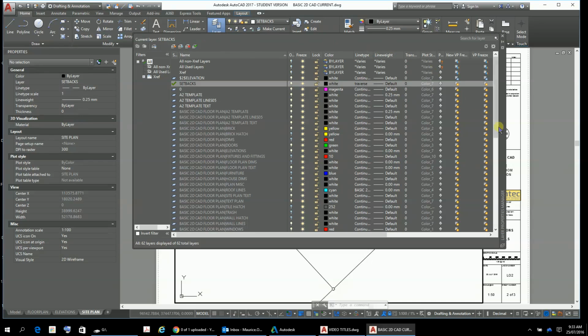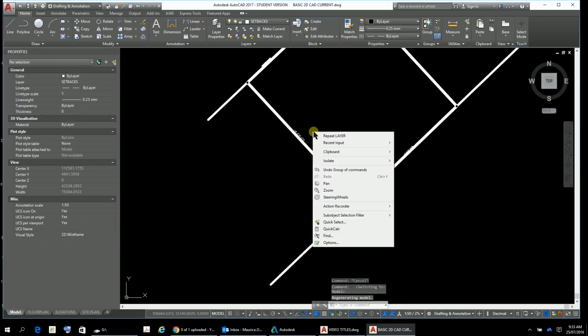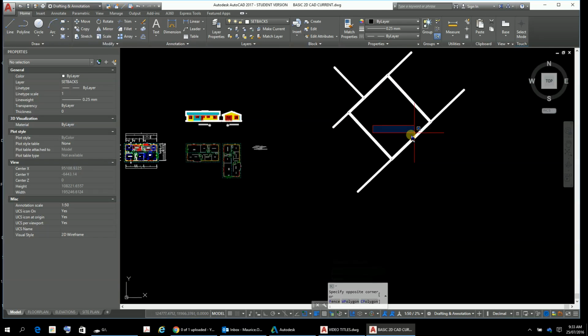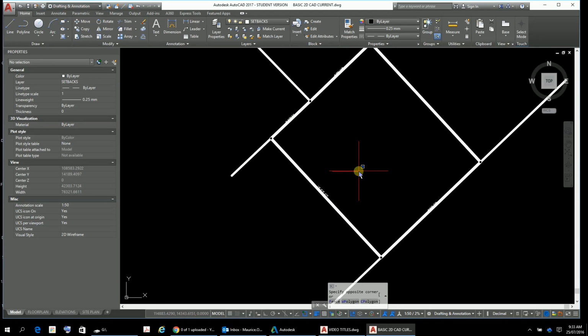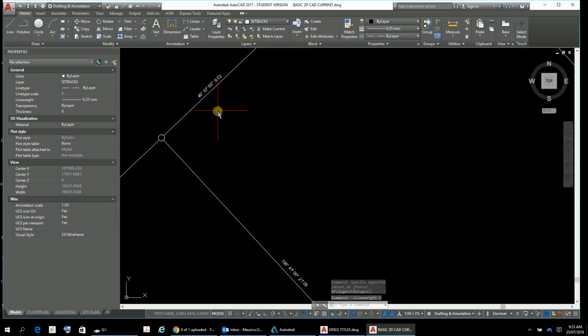So we'll just close that down now, close it down like so. And we can either draw here through the viewport or just go to model space here, and there we are in model space. But because of the way I've got those things set up, with the fatter lines like that, it might be a bit tricky. We could always just turn the line weights off, like so. And there we go. Now, just a straight offset, and when we offset, it stays in the thing.